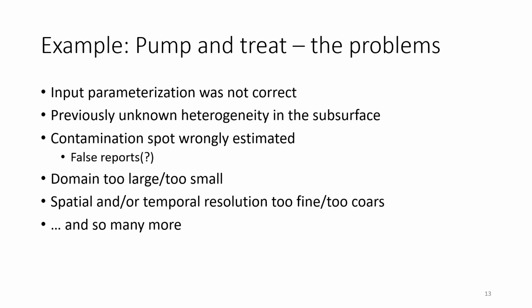And then the coming problems. Even if you validated your model correctly, you might just notice, okay, the assumption of a homogeneous subsurface doesn't hold, doesn't explain my concentration. Could be something like this, right? Or the hydraulic conductivity that was estimated, I don't know, from pumping tests or maybe through laboratory tests, doesn't explain what I see in the field.